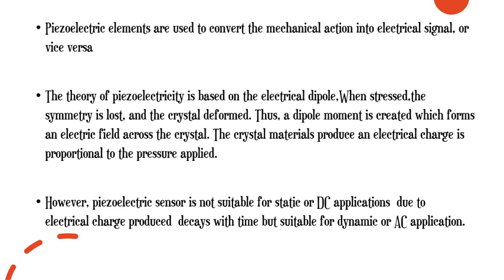Piezoelectric elements are used to convert mechanical action into electrical signal or vice versa. The theory of piezoelectricity is based on the electrical dipole. When stressed, the symmetry is lost and the crystal is deformed. Thus, a dipole moment is created which forms an electric field across the crystal. The crystal materials produce an electrical charge proportional to the pressure applied. However, the piezoelectric sensors is not suitable for static or DC application due to electrical charge produced decays with time, but suitable for dynamic or AC application.